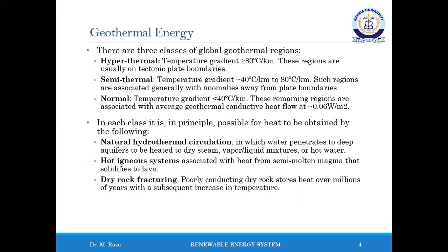Geothermal information has been obtained from mining, oil exploration, and geological surveys. Therefore, some geothermal information is available for most countries. The most important parameter is temperature gradient. Accurate measurement depends on leaving the drill holes undisturbed for many weeks so that temperature equilibrium is re-established after drilling.